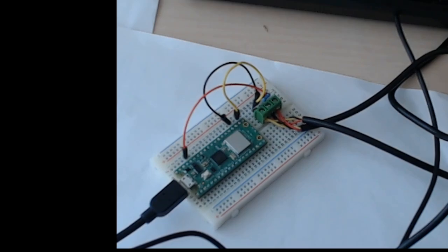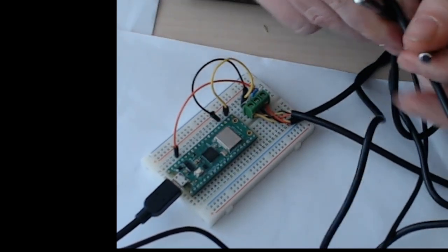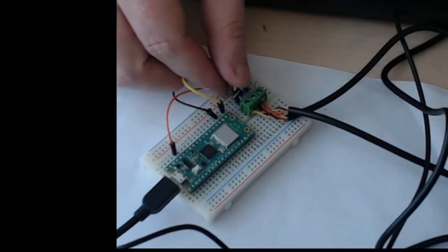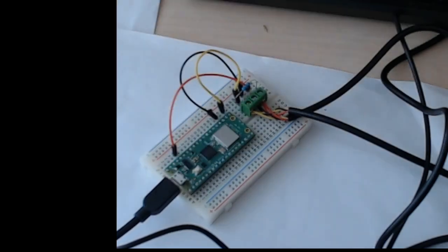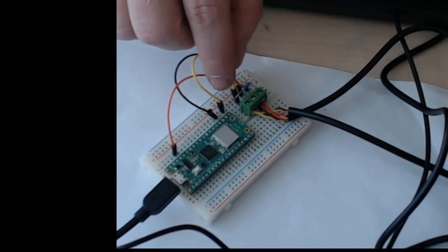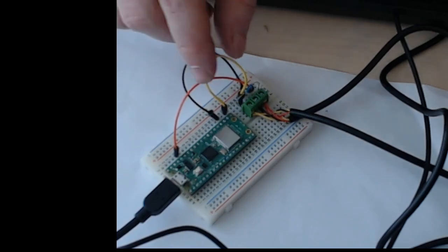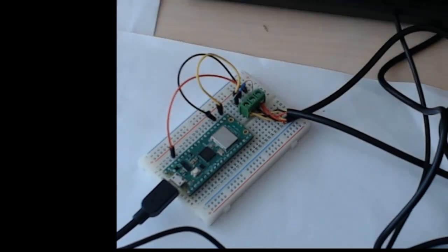So here are my connections. I have 2 of these sensors that I connect. You see here the resistor, and I connect the red one to the 3.3 volts, and the black one here to the ground, and the yellow line here to the GP16, the data line. And you see here the resistor between here to make the sensors read data properly.